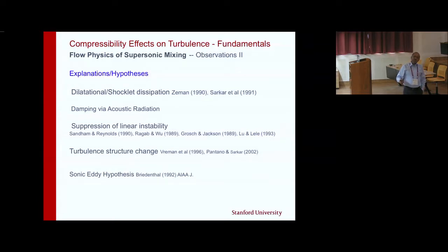Another popular idea in the late 80s was that shear layers radiate sound, and that sound would carry energy flux with it, and maybe it is that which is causing growth rate suppression. But again, one can do an energy budget, find out how much power is being transmitted by acoustic radiation, and that is very small, extremely small, even much smaller than this dilatational and shocklet mechanism.